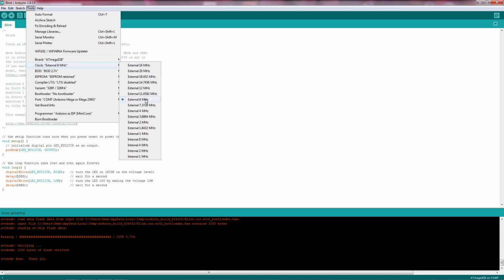That's because certain characteristics of the internal circuitry that oscillates with the crystal are adjusted to better match certain ranges of crystals. But it says nothing about the speed. If I had a 16 MHz crystal in there and I chose the 16 MHz and burned the fuses, guess what? It would be the exact same fuses, because it's any crystal in this range.